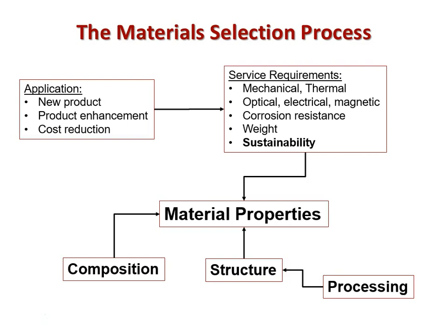Well, your material properties come from two places. One is composition, which basically encompasses the three basic material classes, metal, ceramics, and polymers, and from structure. How those atoms are put together, directionality, how the bonds are arranged, multi-phase structures versus single phase, how much void, grain boundaries versus single crystals, crystalline versus amorphous, etc. And then the macro structure that would be involved in forming a composite.